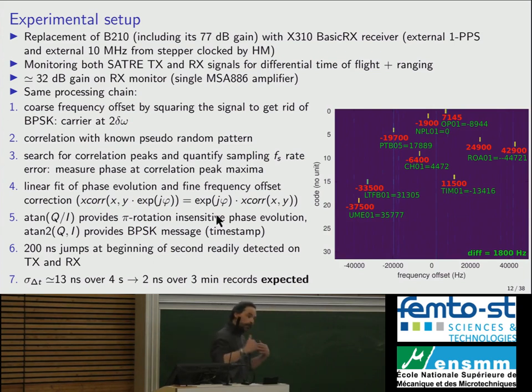When you look at all the received signal, you can find the codes of all the European observatories and the frequency offset. And you realize that all the frequency offsets are a bit off with respect to their official value. That's a frequency difference between the expected frequency and the real frequency of the satellite sending the signal back to Earth. So the satellite is a bit off with respect to its nominal frequency. But you can find all the European observatories, and then you can timestamp the Besançon time with respect to the remote observatories using post-processing of a recorded signal.